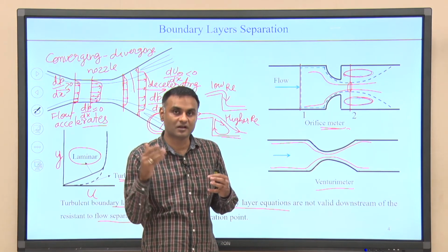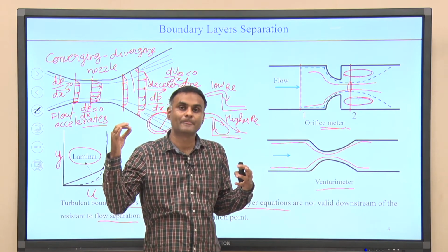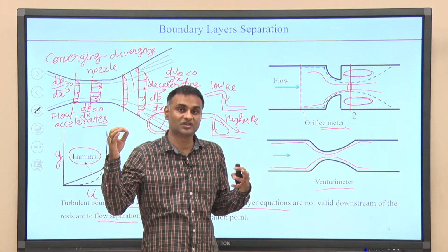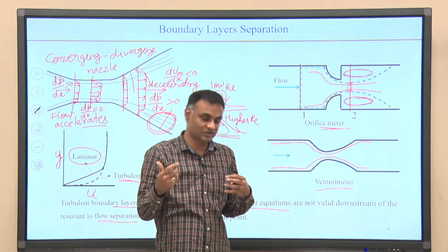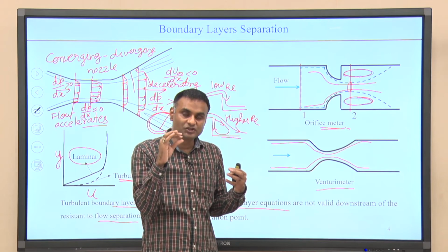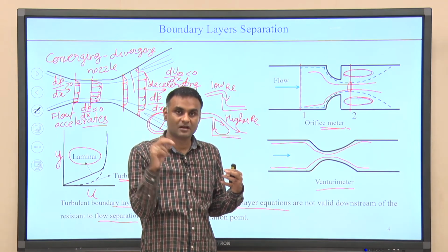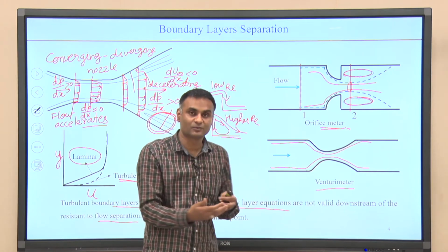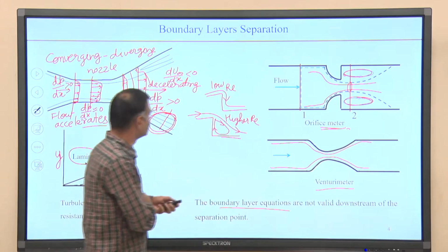Whereas in the boundary layer equations we derived, u is significantly greater than the y component of velocity v. This came because we could assume that the boundary layer is very thin, and that will not be valid anymore when the flow separation occurs. So, we cannot use those equations.